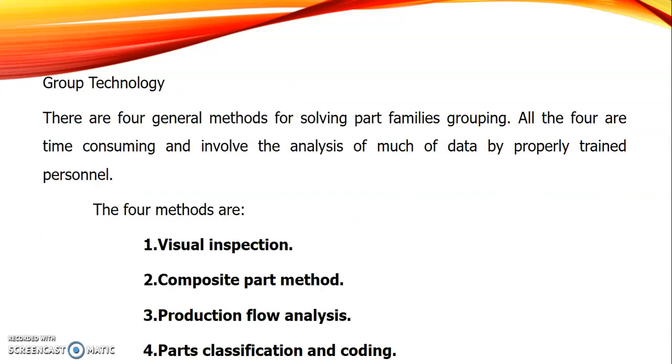There are different methods to identify the part families. They are categorized into four methods: visual inspection, composite part method, production flow analysis, and parts classification and coding.